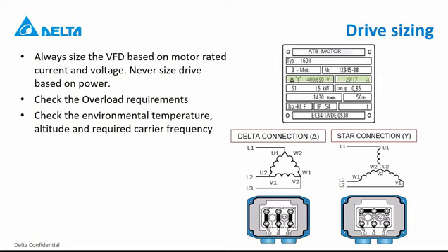This is something you have to keep in mind for basically any electronic device, not just for variable frequency drives. But what is specific to drives is the carrier frequency derating. Of course, it makes sense that if you use a higher carrier frequency, then the drive is working a lot more and generating a lot more heat. So if you need to use a carrier frequency which is above the rated one of the drive, we also have different graphs in the user manuals which you can consult to see which derating is actually needed.